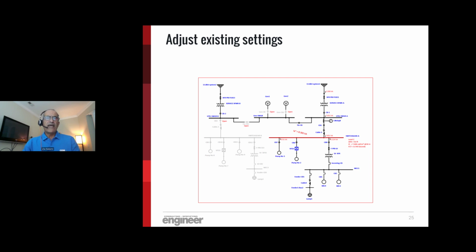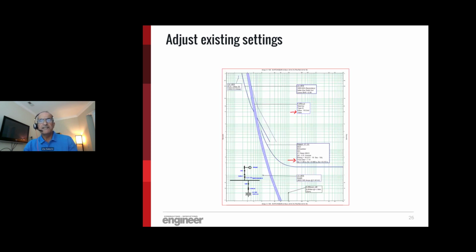But realizing that I had more space, I brought my relay down. Remember that the lower fault clearing time causes lower arc flash, because we are holding the energy for less time when the relay releases, therefore it will be less. Now, in this TCC, we changed the time dial on the relay, brought it down to around 1.14.